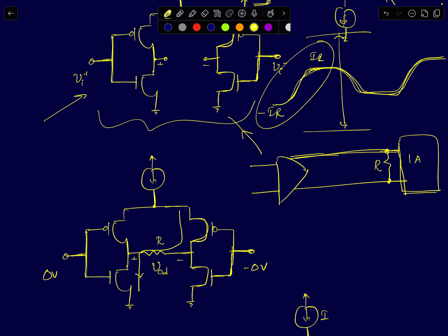I can connect an instrumentation amplifier, right? An instrumentation amplifier will amplify differential input voltages and provide a single-ended output, even if I provide, let's say, a gain of 3 to 4. Normally your differential voltage signals will be in the order of a few hundreds of millivolts. Multiplied by a factor of 4 or 5, depending on your supply voltage, you can then appropriately choose the gain of the instrumentation amplifier so that the output voltage reaches the rail-to-rail voltage levels. I'll come back to this discussion.